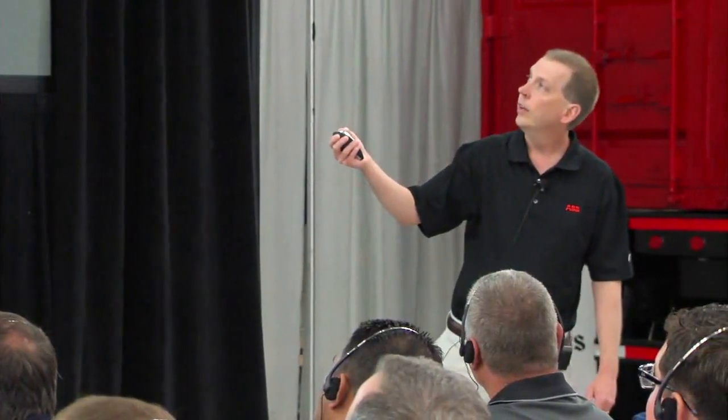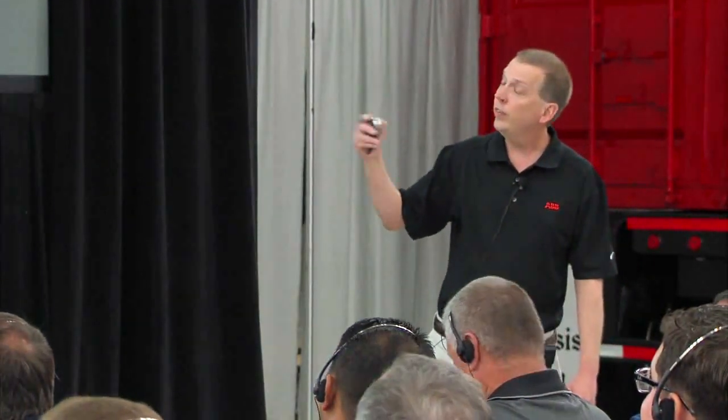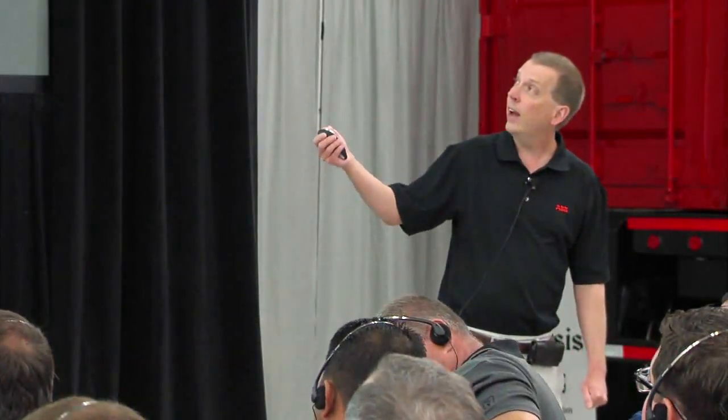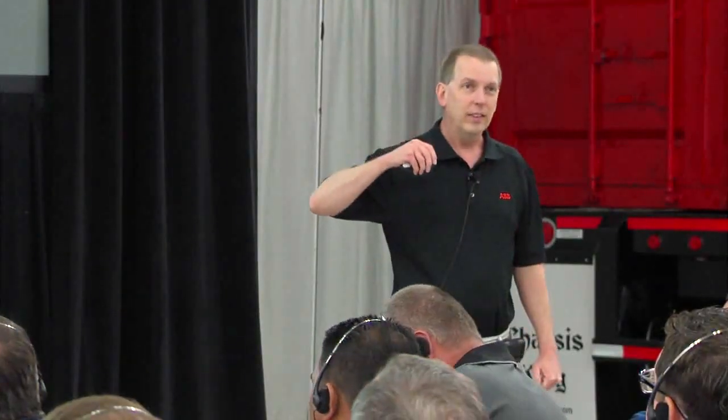There's also a way if you need a lot of torque to break something away. If you have a very high stiction application, maybe a heavily loaded rock conveyor that you've got to get started, you can pre-magnetize the motor with what's called a DC magnetization. You can kind of prime it, if you will. Then when you hit it with the start command, it's going to have all possible torque, and it's probably going to break that load free.